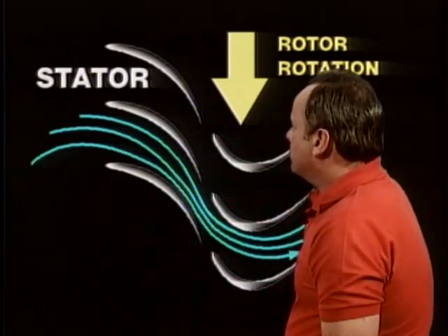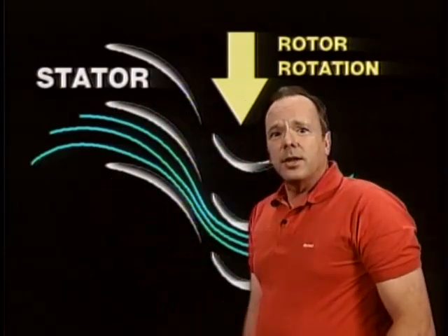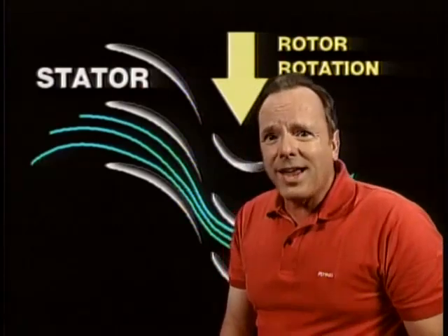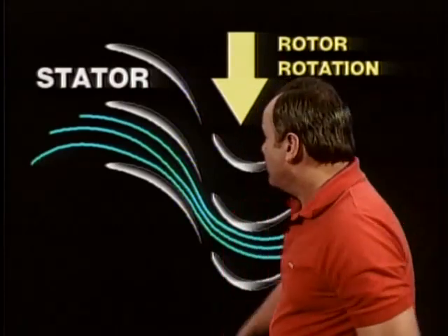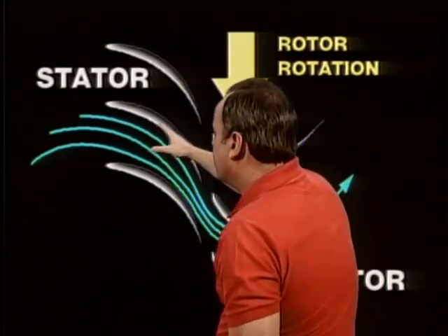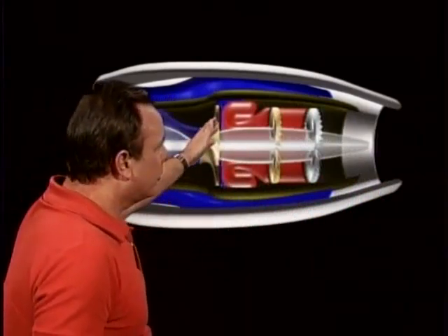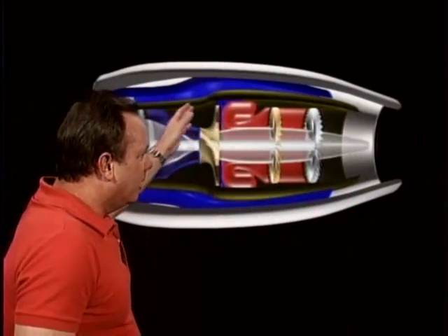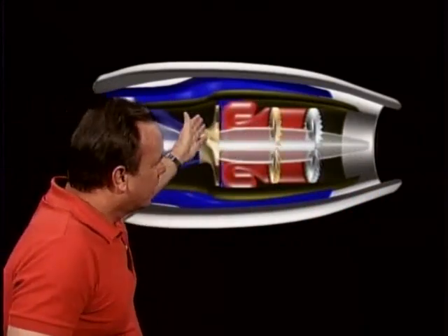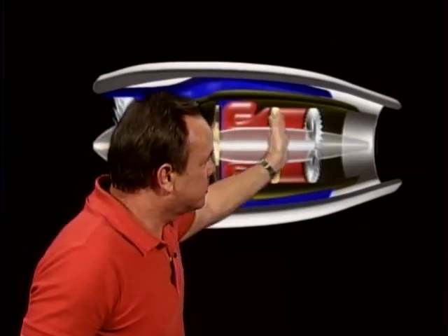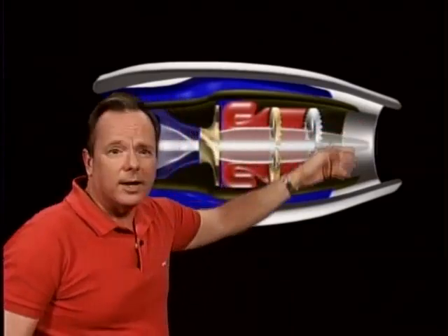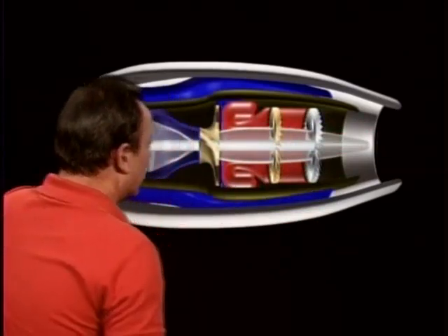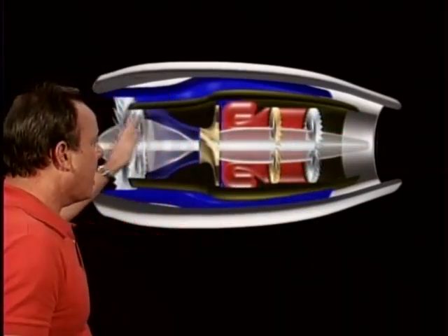The hot section of a turbine engine is particularly susceptible to what is known as cracking damage, and cracking damage will come because of a tremendous amount of heat. Of course, the hot section begins when you add fuel to the air in the burner can and you have flame going on. That really hot air now goes past the turbine blades, and the turbine blades are in the hot section of the aircraft. Once again, the compressor blades up here, you're just compressing the ambient air.